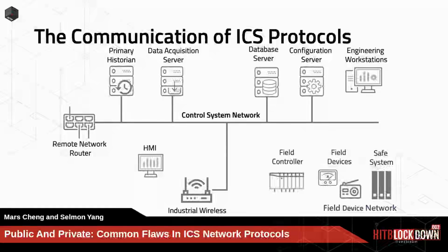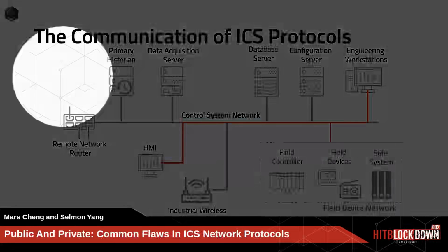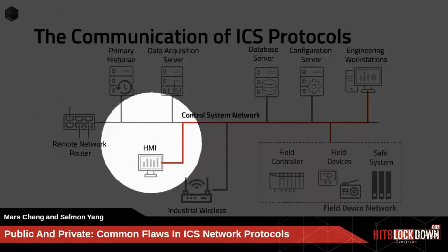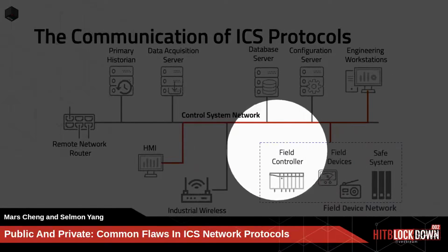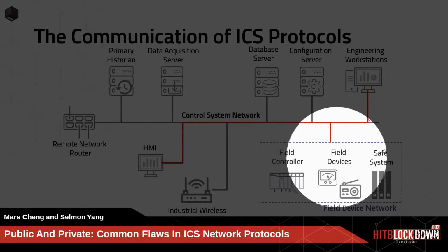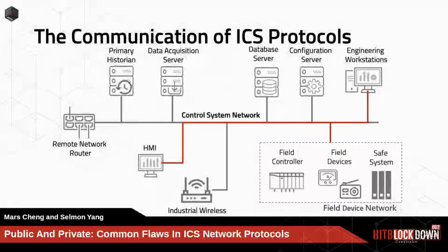So usually we will see our architecture here. We already saw it, but now we talk about the communication protocol usually used between the HMI and the engineering station or field devices. Usually the HMI sends a control command to the PLC, to the controller, and the controller triggers the field devices to do something, such as process monitoring, and so on.